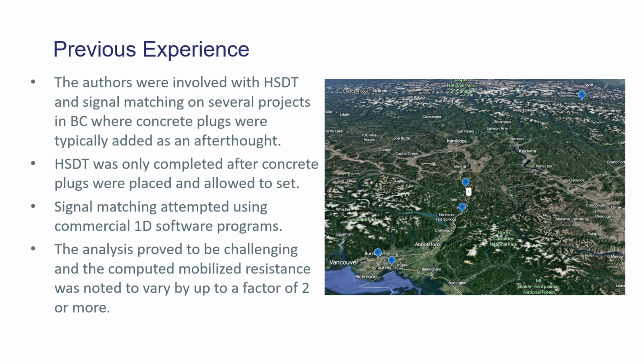The deal is the plugs are often added. Sometimes we think about them ahead of time and say, well, we might need them, or we get to a place where the piles aren't stopping, they're going longer than they're supposed to, so there's potential for cost overrun, schedule, all sorts of stuff. So it's like, hey, let's throw some concrete in there. And then the question is, well, how long should that be? That's the subject of a different paper.